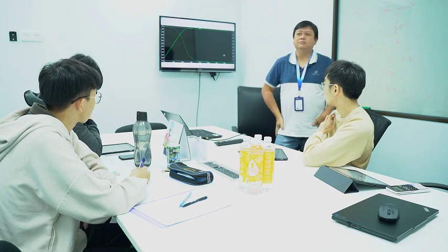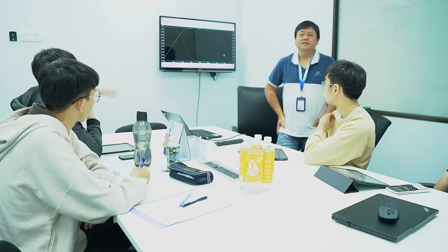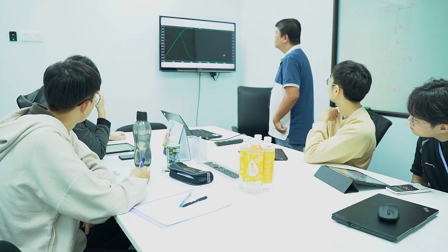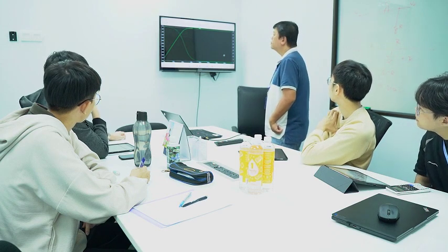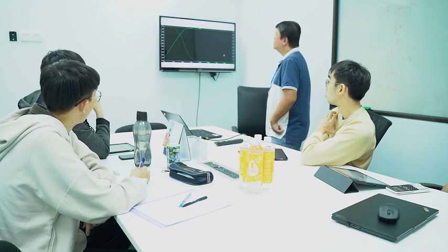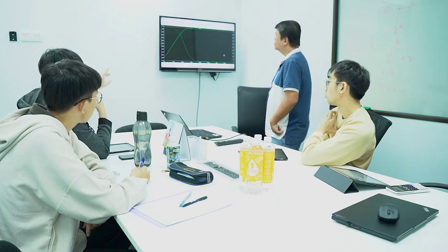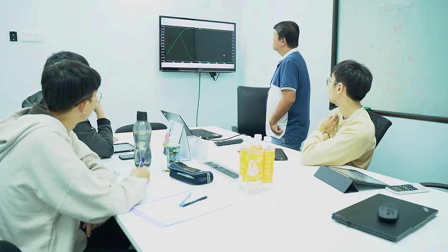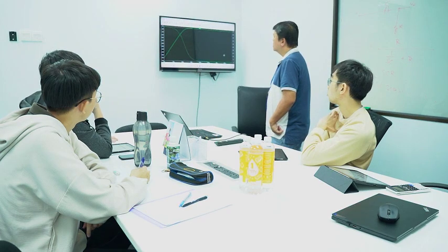Any question to ask about this high pass filter? Yeah, in this case, the zero here at the origin, is it a right hand pole? Because when you go up the slope, it will be plus 20 dB, but then your phase shift will decrease over time. So in this case, it will be a right hand pole. It should be right hand. Okay, right hand pole.